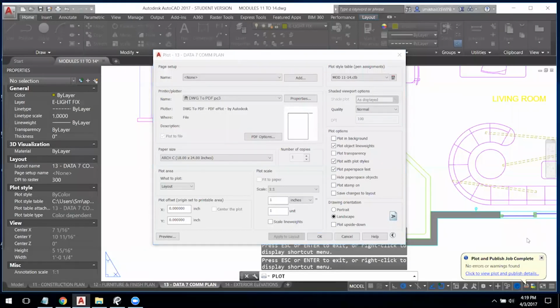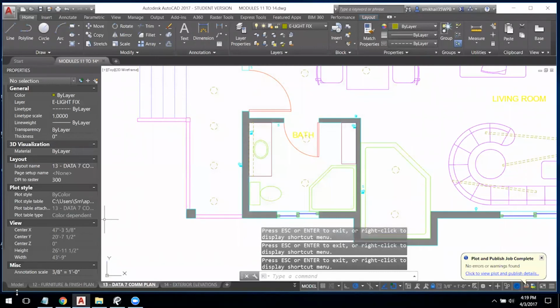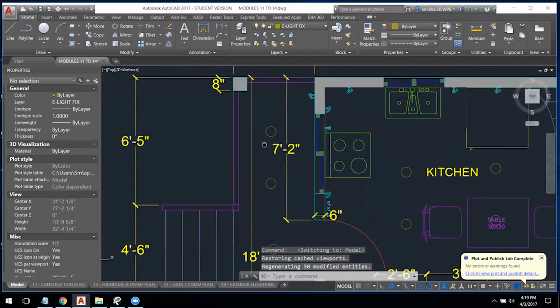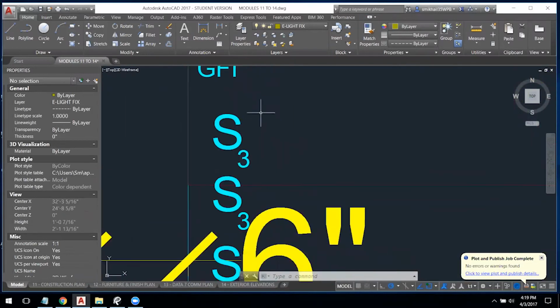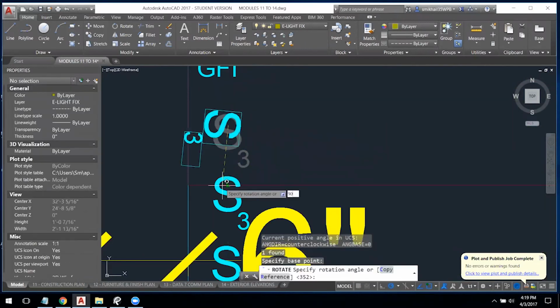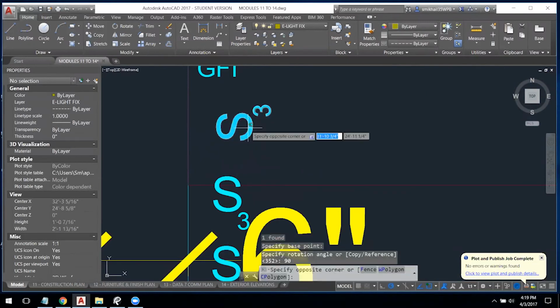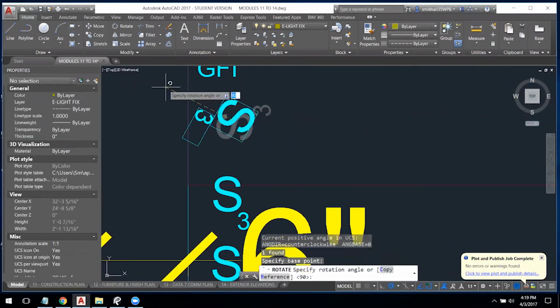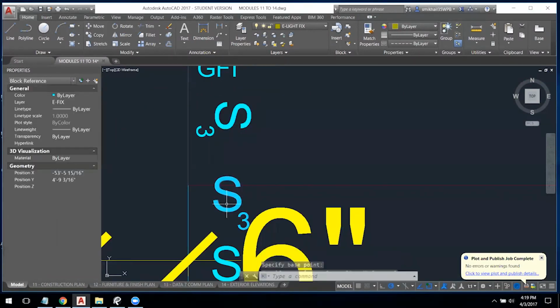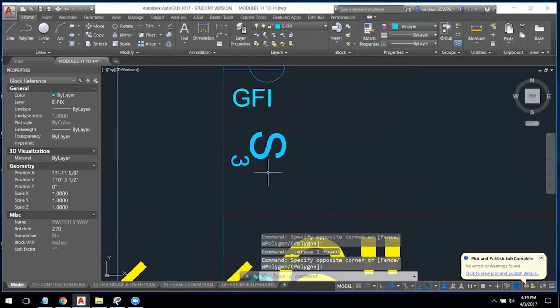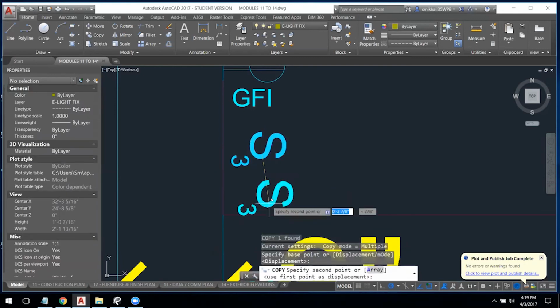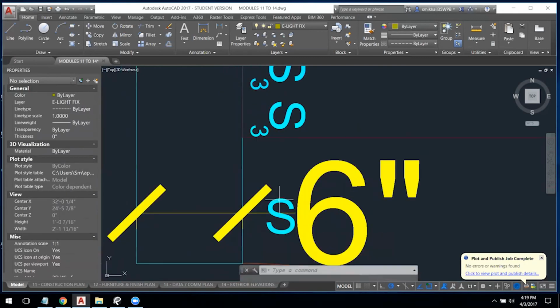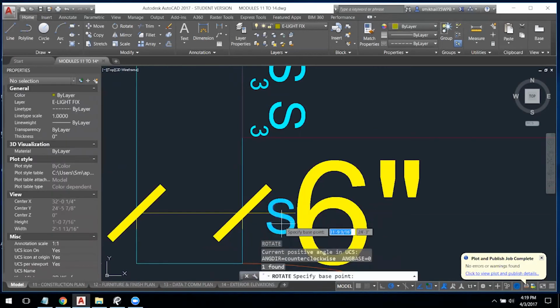Now, one thing I definitely want you to do is fix the switches around your floor plan because it starts to look very confusing. Just having an S there like that looks very odd. So one way of doing this is to actually rotate the switch 90 degrees, and then you can take the switch and put a line right through it and make that line touch the wall. So basically, this is what it would look like. I will rotate this 90 degrees, and I will copy it because I have two three-way switches in here. I'll take this one as well and rotate it 90 degrees.